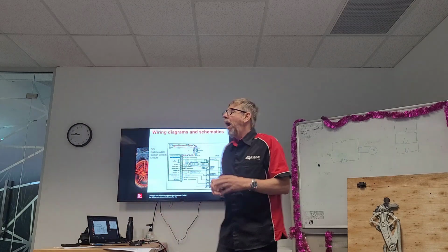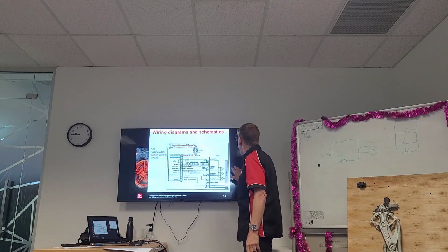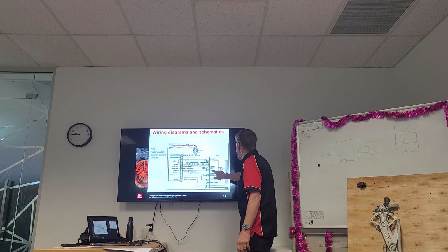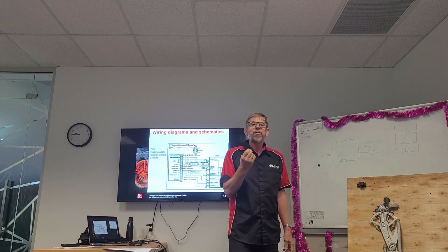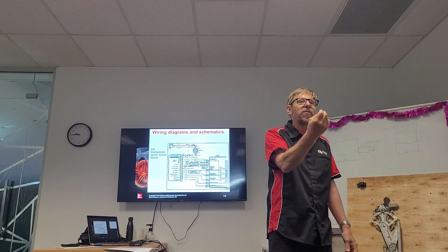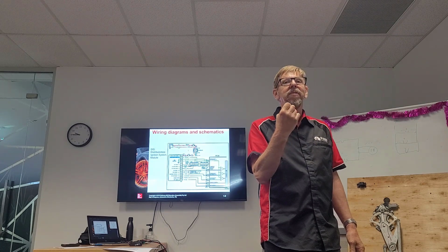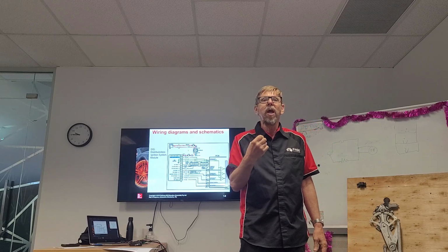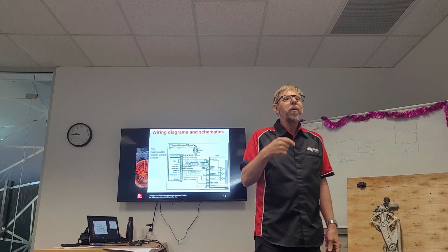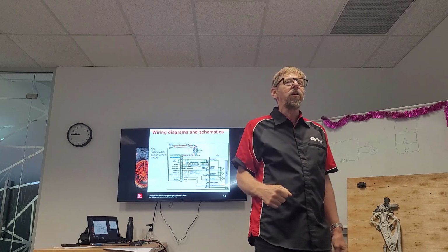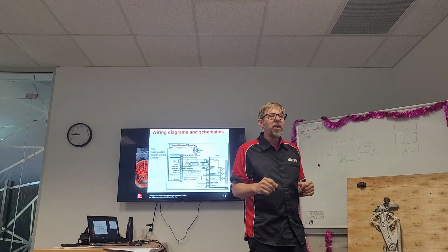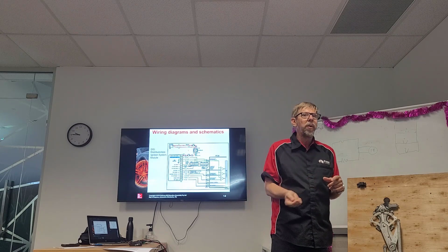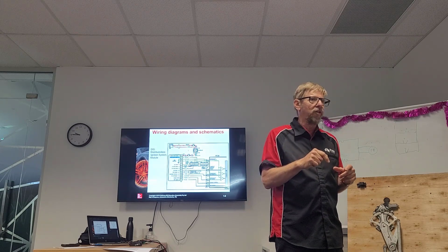Inside the computer, the signal comes in, and each transistor for that signal, for the cam angle signal or cam sensor signal, crankshaft sensor signals come in. With that information, it will then send a signal back to the ignition module. The ignition module will know at what time then to ground the coil. When it grounds the coil, it sparks the ignition, okay?